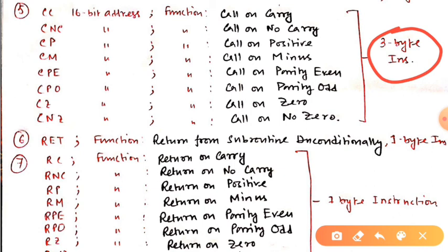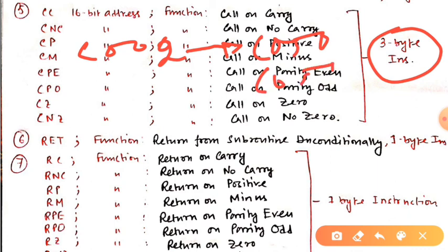As we have seen in our previous example, after the C002 memory location, from the main program we have shifted to the subroutine at the C050 memory address, and we have kept the subroutine there in the subsequent memory locations C051, C052 and so on.